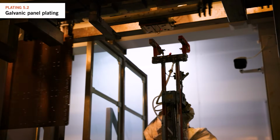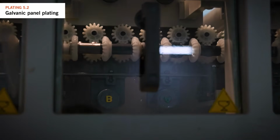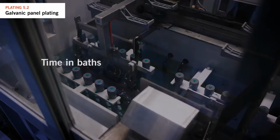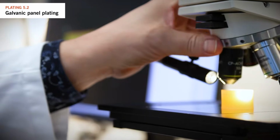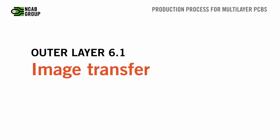To ensure quality, factories must use reliable and well-known chemical brands for the plating chemistry and have good process control, as well as good management of all other plating parameters, including time in baths and control over plating currents. We also expect at this stage deposit rates to be checked, as well as surface through-hole thickness of deposits.